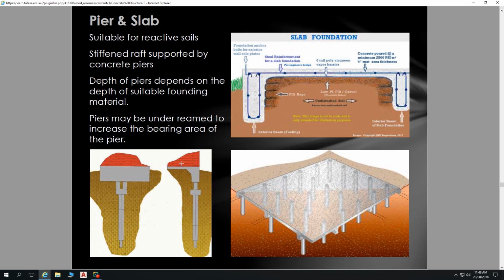And there's several different ways of constructing piers as well. They might be piles rammed into the ground, and in places like Amsterdam, construction sites in that initial process are very noisy because you've got these pile drivers going whack, whack, whack, driving these piles down into the ground, which they then build on top of because they've got some very sloppy soil there. But there are also screw piles, if I mentioned screw piles before. So you can screw them down into the ground and use those in conjunction with slabs or elevated slabs, etc.